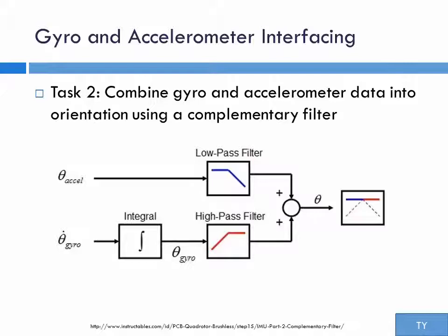But this degree value tends to drift over time because the noise is accumulated with degradation, so the gyro's reading is only accurate for a short time. This is the reason why we introduced the complementary filter and included the accelerometer in the measurements. So in the short term, we use the data from the gyroscope because it is very precise and not susceptible to external forces. In the long term, we use the data from the accelerometer as it does not drift.